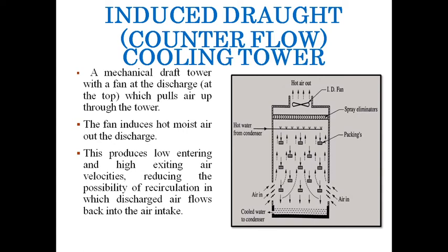Next one is the packing. This packing is located below the water spray or water distribution layer and above the sump of the cooling tower. It is also referred to as heat transfer pack. Purpose of this packing in this cooling tower: it provides large surface area for evaporative cooling to take place.